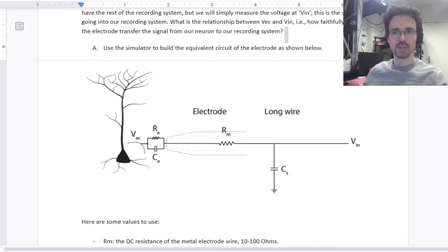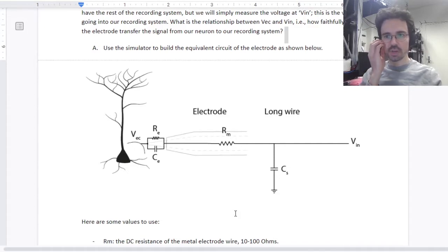Hi, I'm Jacob. I'm going to give you a quick overview on how we're using op amps in a very simple way to be able to record small signals from the brain. Particularly in a neuroscience application, we're often dealing with signals that are not only small in terms of voltage, but they cannot source a lot of current. So we would say that they have a very high output impedance. These are terms that you've likely already talked about earlier.